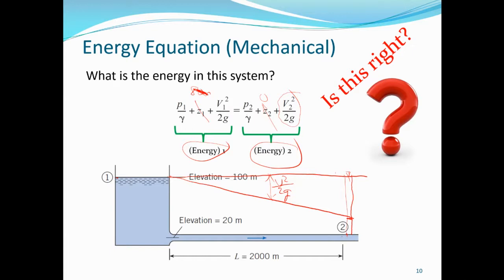But then, as we are going to see later, as the water is flowing, it is losing head. It is losing pressure head. This is the head loss, okay? This is the result of the head loss. You can see the head here is up to this point. When you put a piezometer, the head is supposed to go up to the height of the water in the tank here. But there is head loss, which is the difference in head here. That is the head loss, okay?